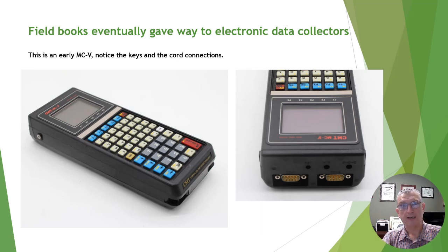Surveyors would go back out to where there was a known angle. I've known of surveyors that set up a point in their office where they could backsight a billboard a mile away and turn to the center of a radio tower 3 miles away. Those points were not going to change. That was an angle that was repeatable to 1 second. And they had turned it with a Wild T2 theodolite. They had done it with some of the other early theodolites.